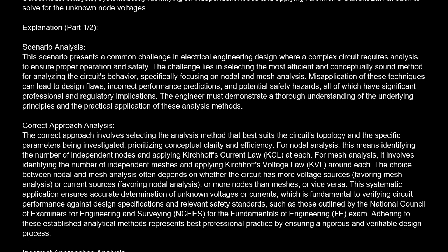Correct approach analysis. The correct approach involves selecting the analysis method that best suits the circuit's topology and the specific parameters being investigated, prioritizing conceptual clarity and efficiency. For nodal analysis, this means identifying the number of independent nodes and applying Kirchhoff's current law, KCL, at each. For mesh analysis, it involves identifying the number of independent meshes and applying Kirchhoff's voltage law, KVL, around each. The choice between nodal and mesh analysis often depends on whether the circuit has more voltage sources, favoring mesh analysis, or current sources, favoring nodal analysis, or more nodes than meshes, or vice versa.